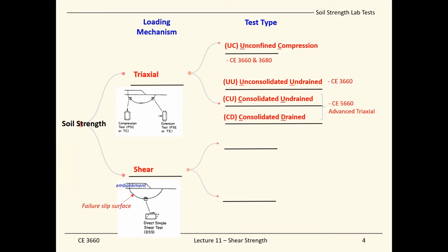They also have sigma 3, the horizontal confining stress, and on top of that, they will also conduct a consolidation phase, which makes them the consolidated undrained and consolidated drained tests. Along with those, these are the 4 commonly available triaxial tests. Each test in our business also comes with a cost and the time needed to finish it. The unconfined compression test is the most straightforward, so it's easy to conduct, but it also has its shortcomings. But it's a quick and cheap test to be done.